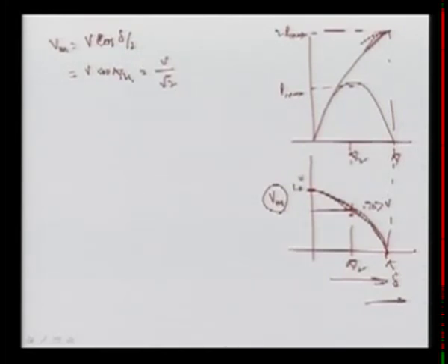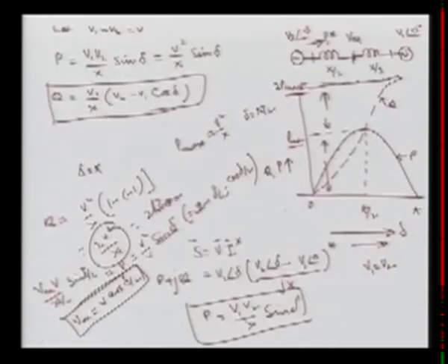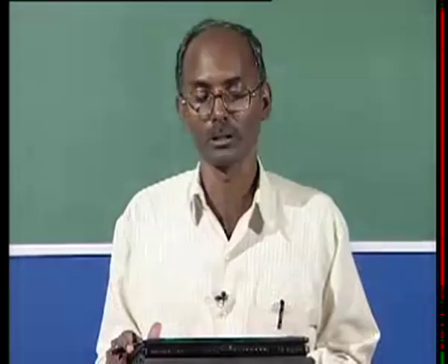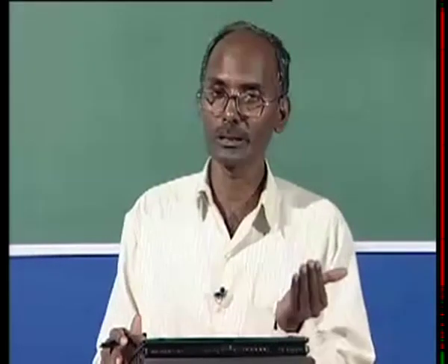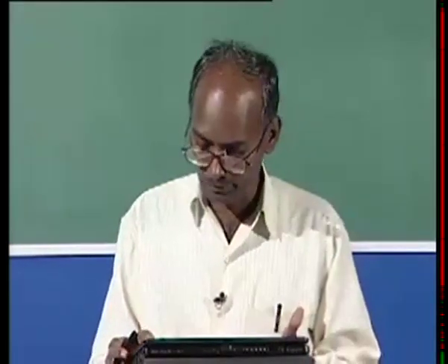Now what I am going to do is maintain that voltage at V by some device here, and that is your FACTS controller. It may be your SVC or STATCOM. With that we can maintain this voltage by varying XC or injecting some reactive power into the system. So we are maintaining the Vm voltage at V, and let us see what improvement we are going to achieve.